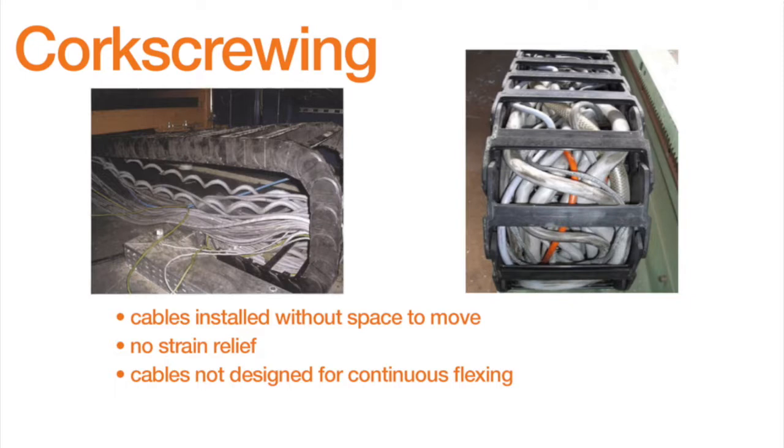And when you get to a certain number of conductors and you're talking about a certain situation with a cable carrier in a moving application, it can be very difficult to even strain relieve and install it properly if it's the wrong cable, so that it doesn't fail.